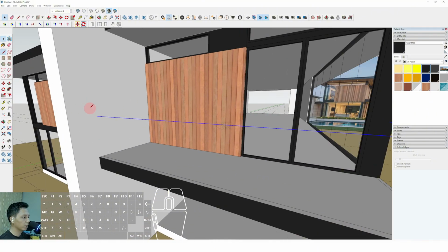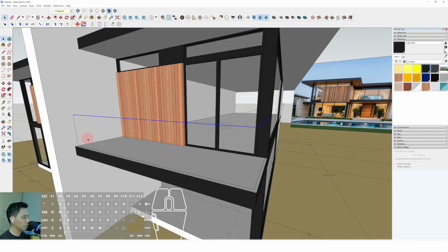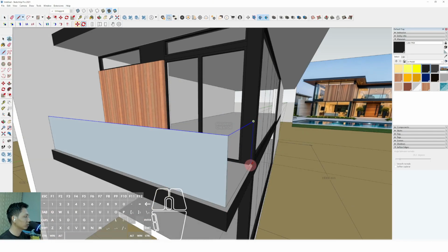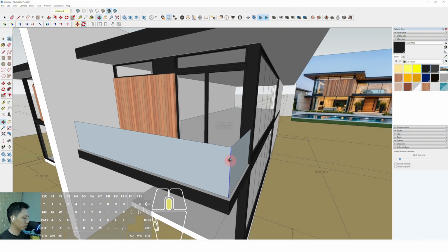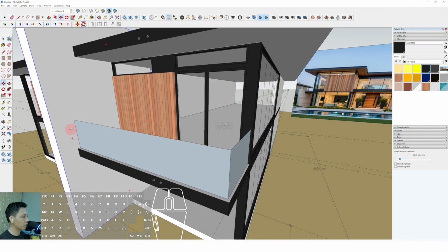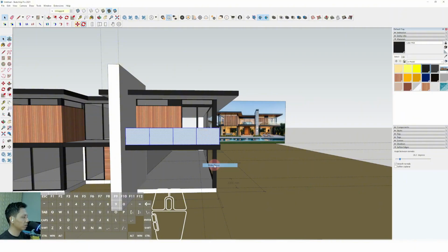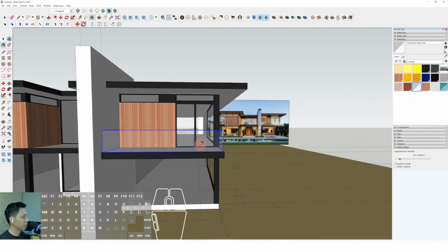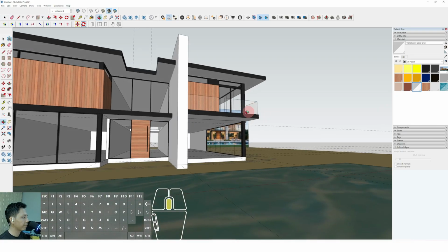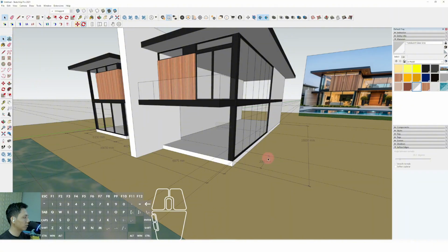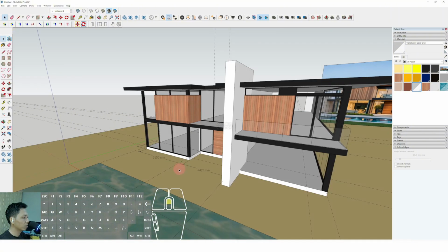Then we can click the line, click from this point until this point. Click this line, select move, tap control, and place this position. Then we can type 4/ and enter. Triple click, make group, and assign the glazing materials like this. Okay, we have to make the additional. I have to erase it first to make it simple for 3D modeling.